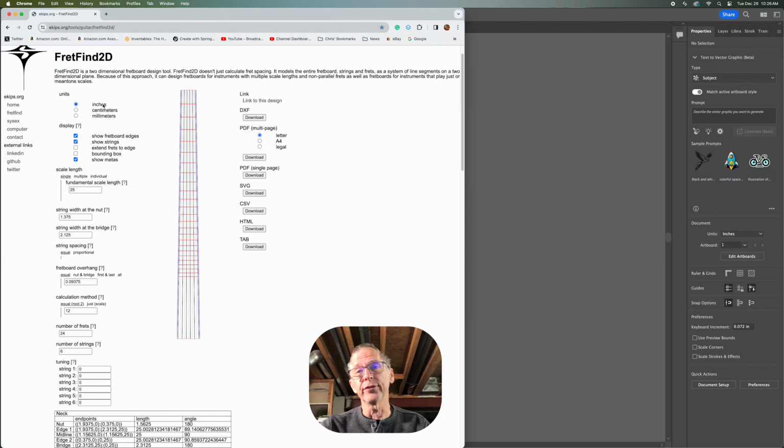I work in inches. It's because I'm here in the United States, and the vast majority of the people watching my videos are here in the United States, so I stick with inches. But you can also do centimeters and millimeters. In the display, you can show the fretboard edges, which I have checked. Show the strings, which I also have checked. You can extend the frets to the edge, and what that means is you can select a bounding box, and that draws a bounding box for this whole image here. And then you can extend the frets to the edge of that. I leave those two options off.